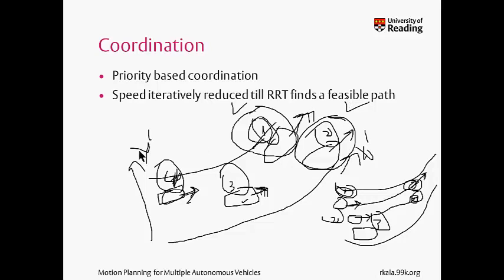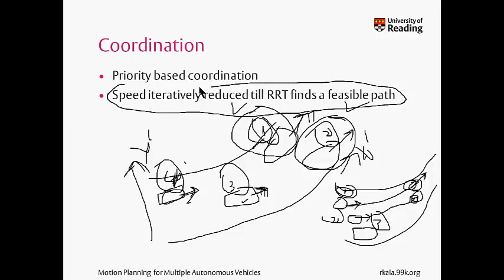Only the lower priority vehicles consider the higher priority vehicles in the trajectory plan, and they can very simply consider, because once the dynamics of the higher priority vehicles are known, they can be treated as simple obstacles as inserted in the general problem solving methodology of the RRT. Now what is important, because it is a multi-vehicle planning problem,